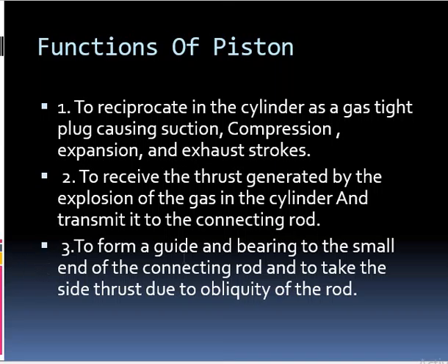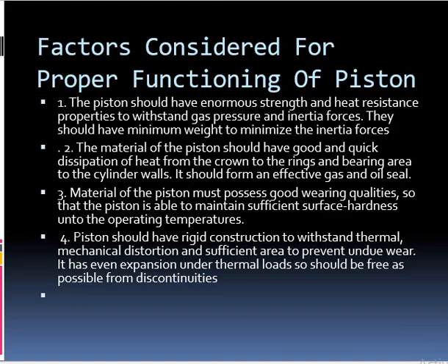Some more factors we will consider for proper functioning of the piston. The piston should have enormous strength and be heat resistant, to withstand gas pressure and inertia forces. It should have minimum weight to minimize inertia forces. The material of the piston should have good and quick dissipation of heat from the crown to the ring bearing area and the cylinder walls.